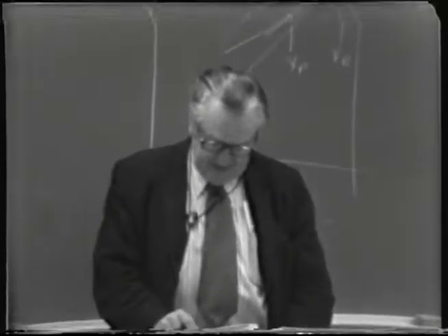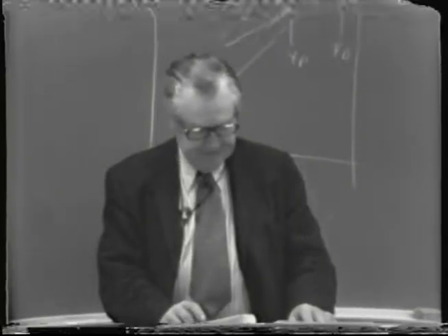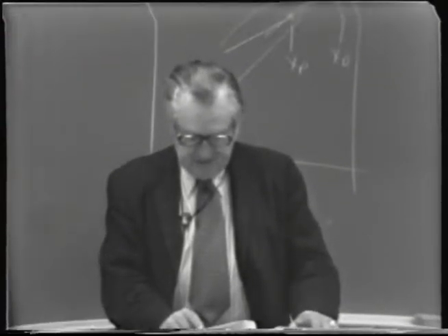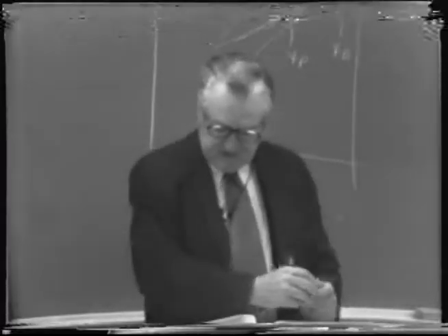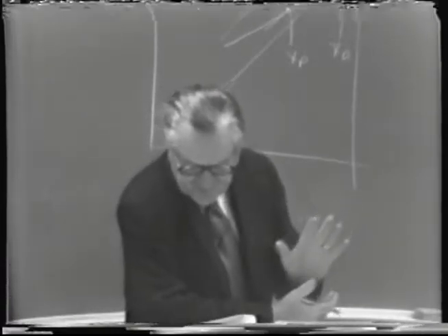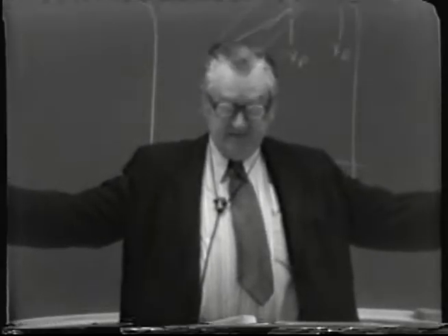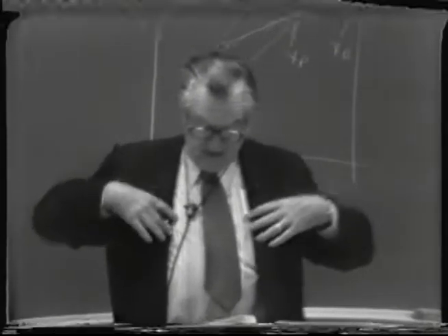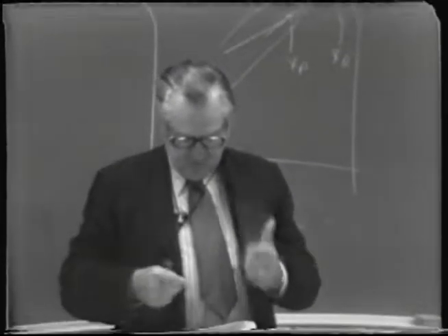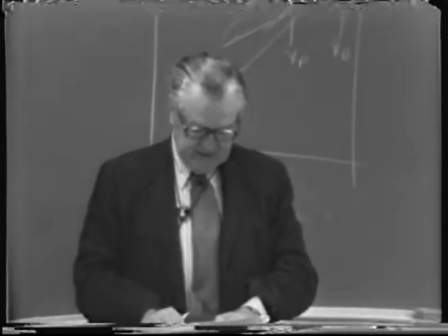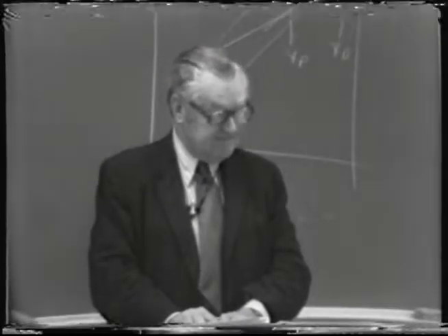And the diameter now, this is something else. This is something that we want to consider that we haven't had before. If the vapor velocity is 2 feet per second, what size diameter do we have to permit this vapor velocity? Well, the easiest way to do that is to work again on a pound-mole basis, and we've already indicated that the vapor rate through this section is 928 pound-moles per hour.